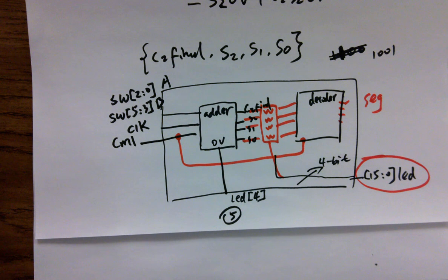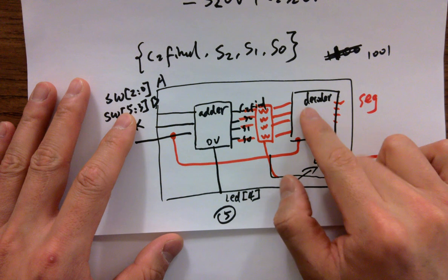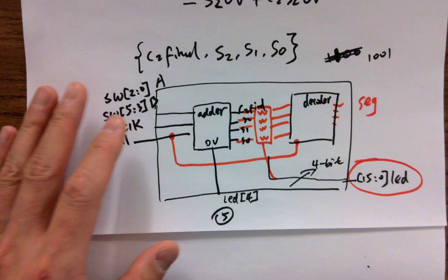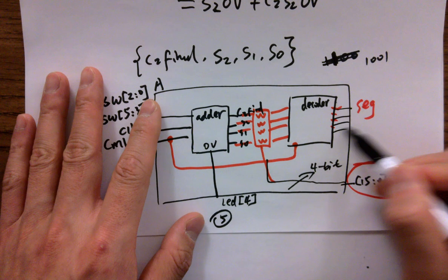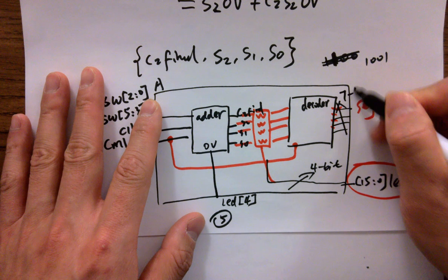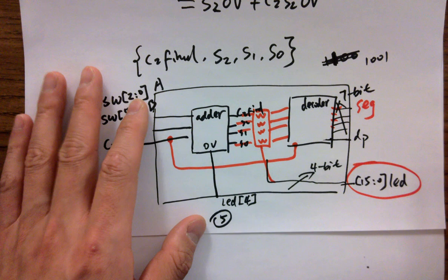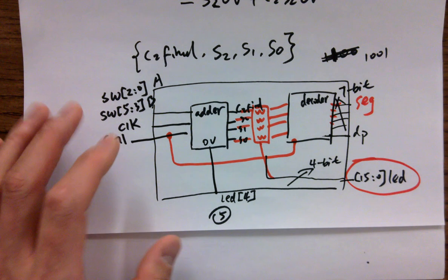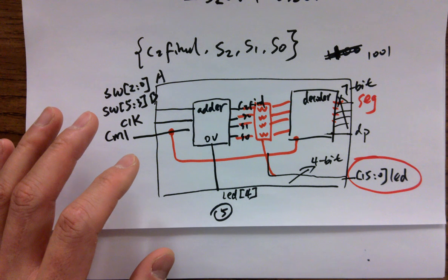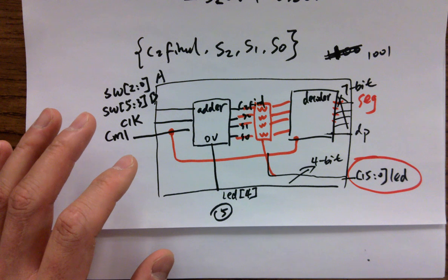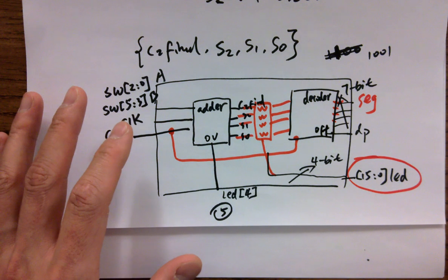Okay, so the decoder takes in that digits input and goes through the case statement of the lookup table or the decoder's patterns. Okay, you have to modify it according to the signed values, and then eventually they are shorted to SAG, right? That's a 7-bit bus, and keep in mind you need a decimal point as well, DP. Just turn it off. Otherwise, it's like having a 2.5 volts. It's a very dim LED. Looks bad. You don't have a decimal point. So control the DP as well. So you need to give DP a what? 1 all the time, right? So it's off. Turn it off.